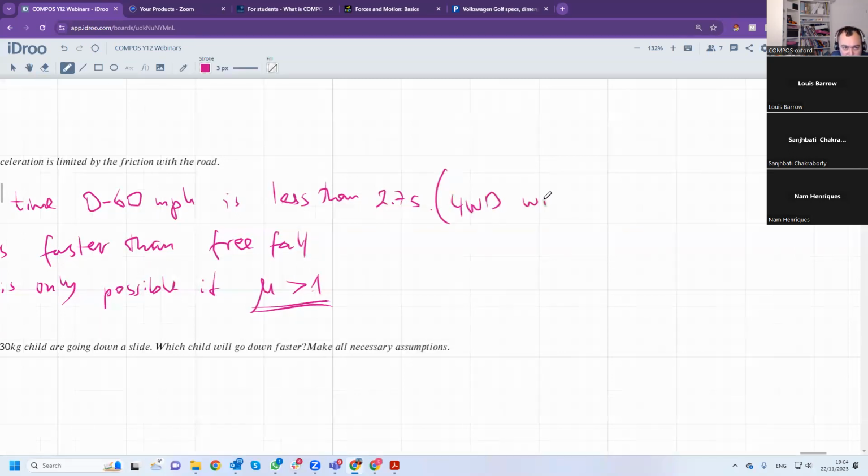There's another factor when the car accelerates: the distribution of the mass is different on the front and back wheels. So there's more force on the back wheels when it is accelerating, and also there's the downforce from the aerodynamics of the car, which pushes the car into the ground further.